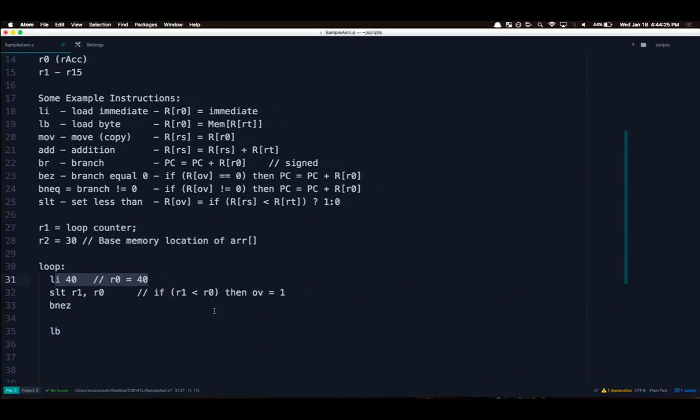So for this load immediate, I didn't want to specify a register. I'm just having it save to that one register. Yeah. So when you work out the details of that in the future labs, where your control signal is, you're going to decode load immediate, and then your control is going to set, you might have a mux for your write register, and it's going to select which register you want to write to by specifying it. And you might just have R0 there as a constant. So the load immediate instruction will select your write register as R0.